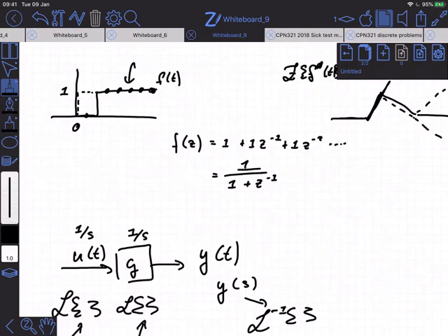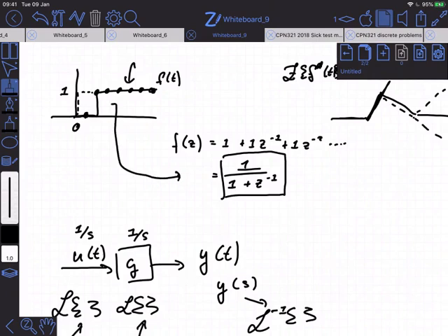Does that make sense to everybody? Because I could express a signal like this, which, let's for argument's sake say this signal is now a shifted version of the step. I could express that as what I know the unit step function is, multiplied by, and that version there would be multiplied by z to the minus 2.